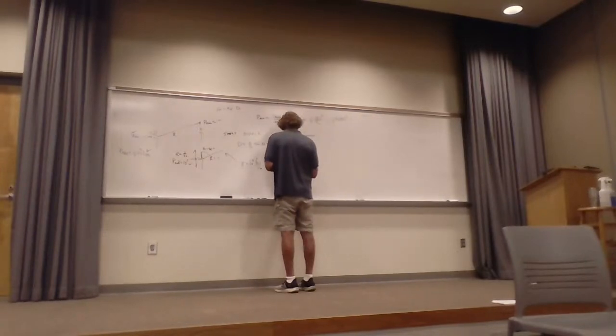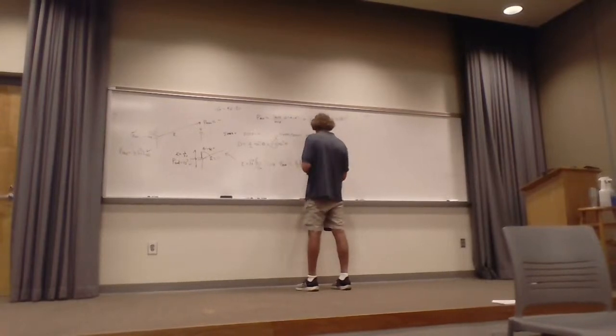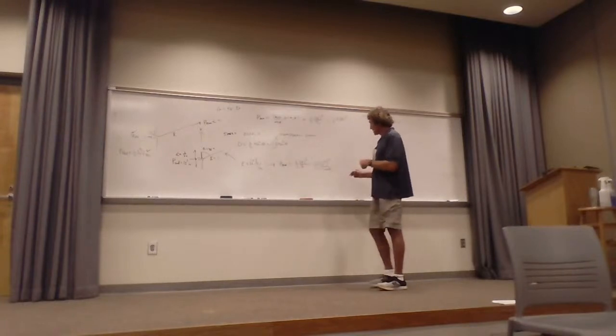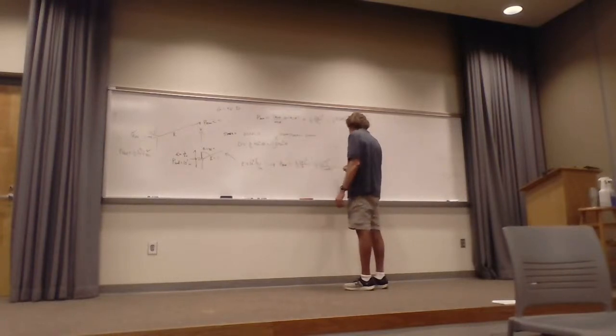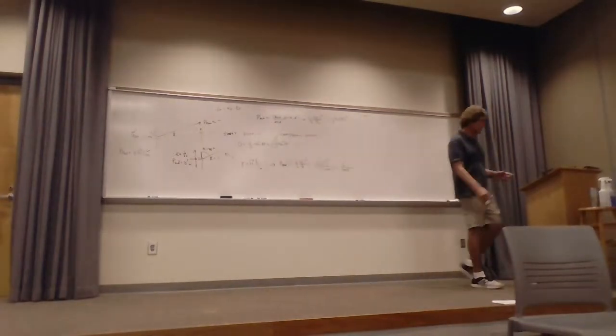So it's 1/2 times the magnitude of E squared over eta. I'm going to just write it down for everybody. This is E squared, 10 to the minus third squared, divided by eta, and eta is 120 pi, right? I can go ahead and do this if you want, but this comes out to what? That's 10 to the minus 6 over 240 pi, isn't it? Correct? And that would be the power density in watts per meter squared.